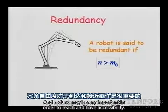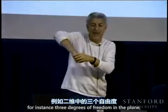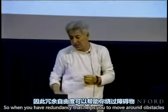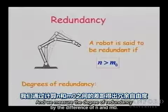And redundancy is very important in order to reach and have accessibility. You cannot just work with the motion of a robot with, for instance, 3 degrees of freedom in the plane. You're going to hit obstacles. So when you have redundancy, that helps you to move around obstacles and position the robot in different configurations. And we measure the degree of redundancy by the difference of n and m0.